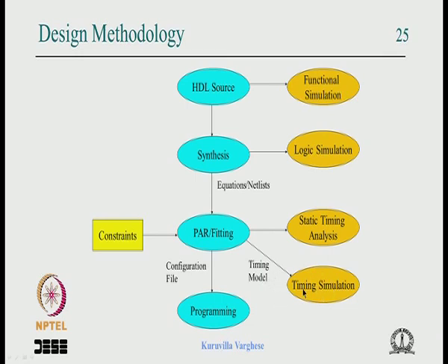So that is timing simulated, but then it takes a long time. One thing to understand is that you give the input, then the simulator has to calculate all the time delays, which is composed of a lot of individual time delays in between. It's not a gross time. It's the IO delay, interconnect delay, wire delays, and the lookup table, the combinational circuit delay, various combinational circuit components, everything has a delay. So there is quite a lot of computation to do, and the timing simulation can be very time consuming.